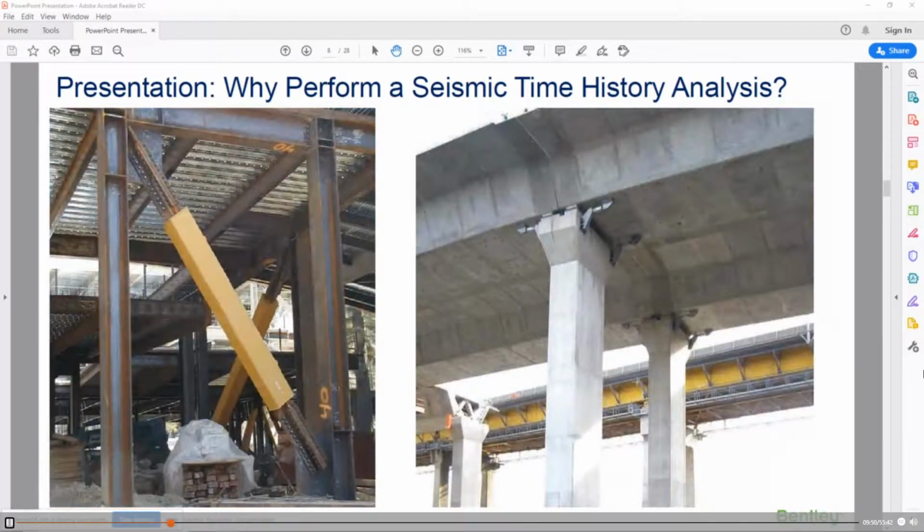one thing we want to do for safety is, once we've evaluated our seismic loading, we want to ask: do we need to implement any different structural elements into our system that is going to help this structure perform better? So there's several different types of things that we can do. We can put in seismic bracing like you see here.